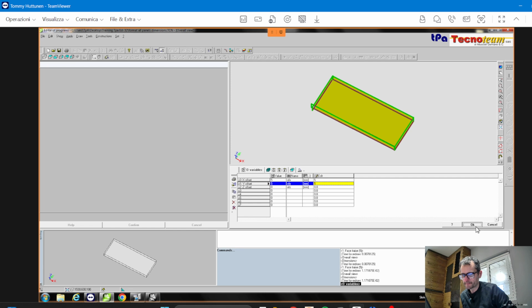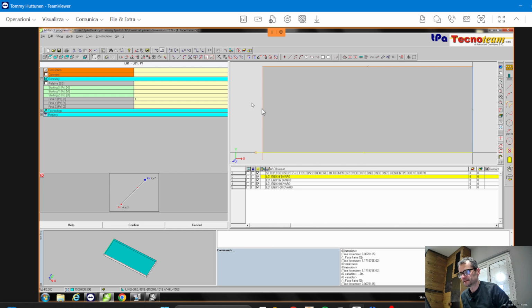What I mean, you don't see nothing, it's just a set. It means the machine will take out here 5 millimeter in this place and 5 millimeter for sure. What I have more, here and here, doesn't matter. Can be 5 if it's 10 more, or can be 4, or can be 6, doesn't matter. What is important is the end dimension is perfect, and that I cut something also here and here. Is that called offset? Yes. Offset means how many millimeter you want to trim here and here.